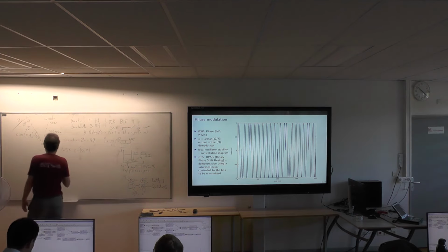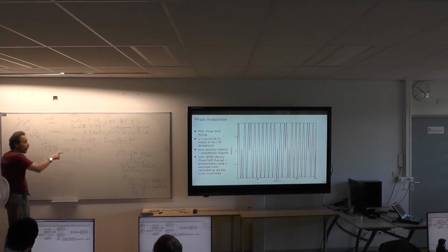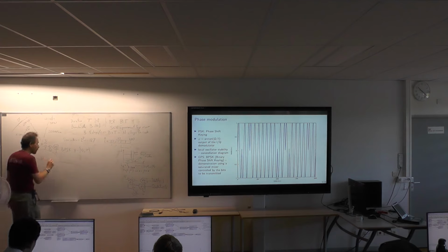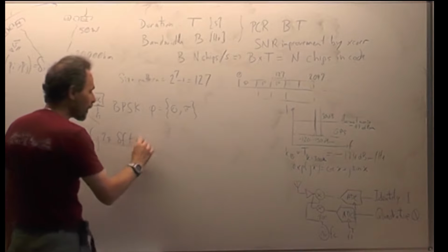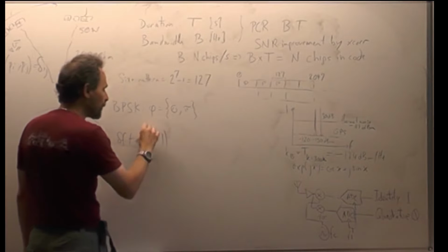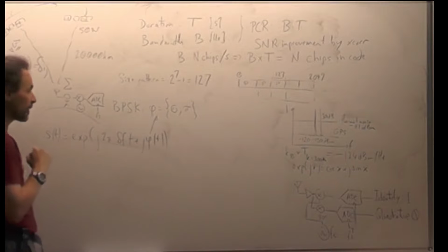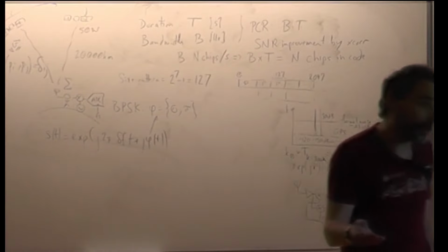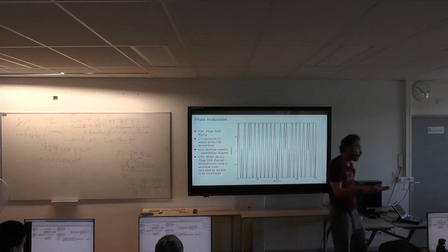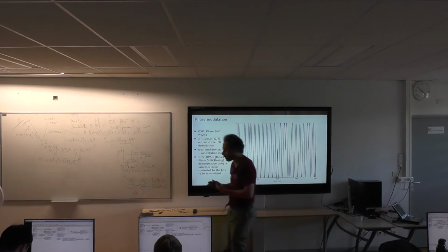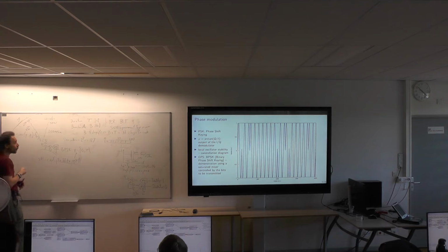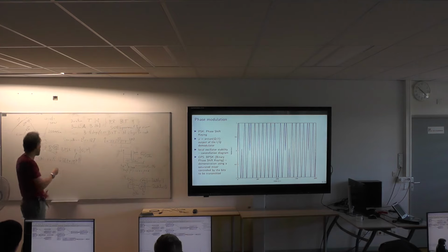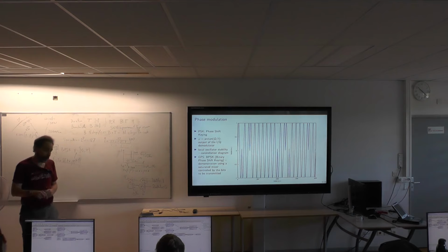It means that the signal that you receive ideally would only include the phase, but it's actually something, we forget about the amplitude because it's all about the phase. So you actually have something that is a leftover e^(j(2 pi delta F t + phi(t))). And this phi is 0 or pi. So you have a leftover offset frequency delta F that you will never be able to cancel, at least not during the acquisition phase, because either you have a very good clock and you have a Doppler shift leftover, or you have a frequency offset between your local oscillator and the onboard oscillator.